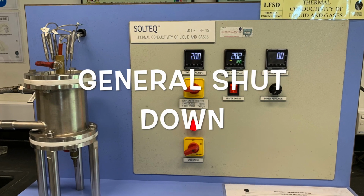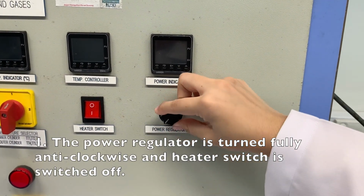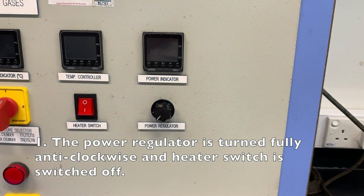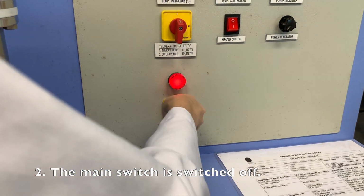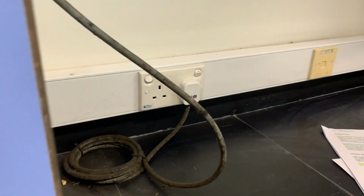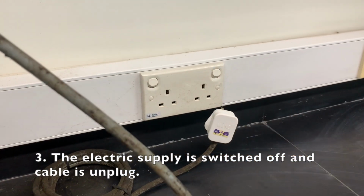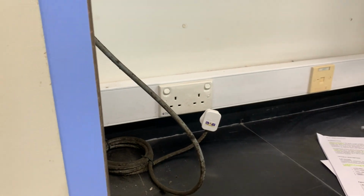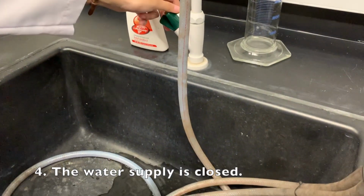General shutdown. The power regulator is turned fully anti-clockwise and the heater switch is switched off. The main switch is switched off. The electrical supply is switched off and the cable is unplugged. The water supply is closed.